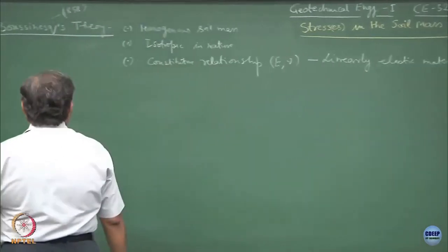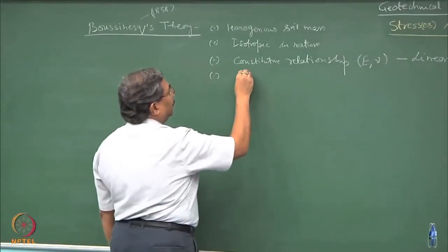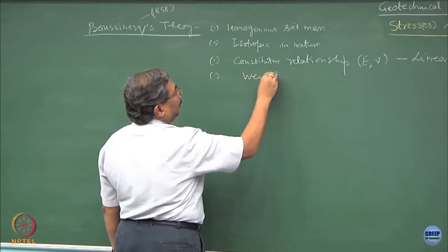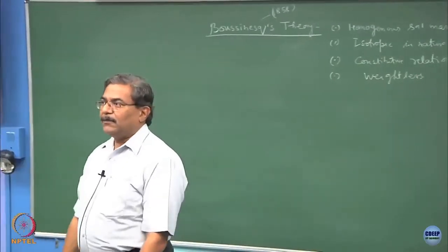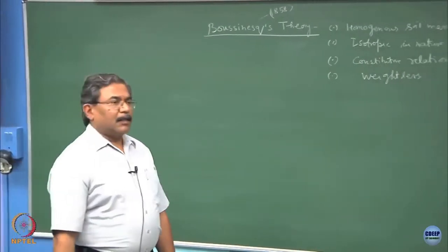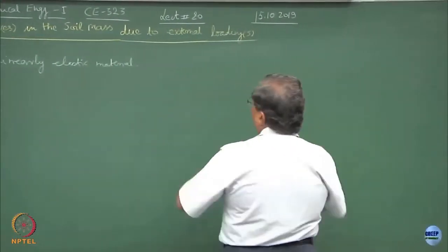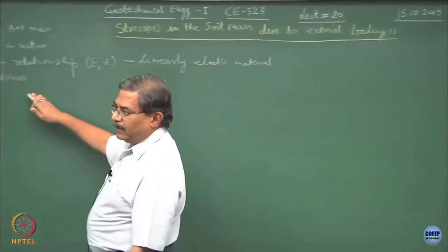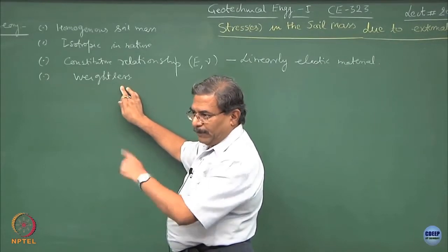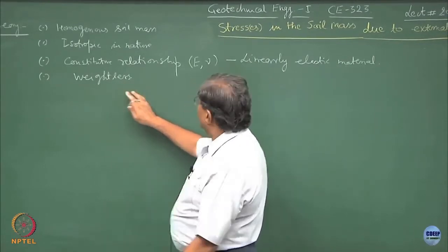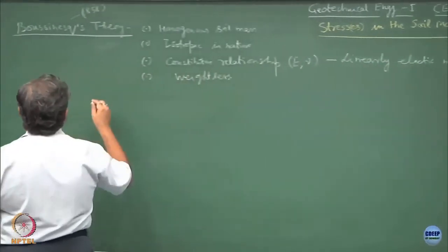Okay. One interesting thing is that this soil mass has been assumed to be weightless. Did you notice this? That the soil mass has been assumed to be weightless. Why? We are making the soil mass devoid of its weight, because weight causes the internal stresses in the forms of either solids or the pore pressures. So, it has been assumed that as if we are computing the state of stress in ether.